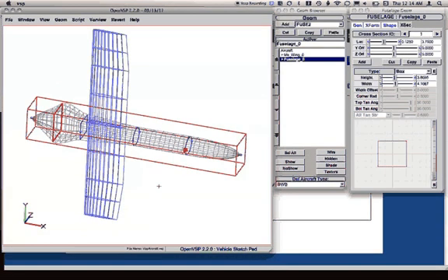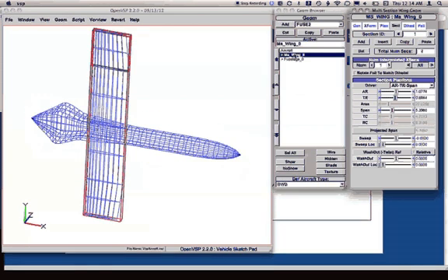Now, different components then, once you get the basic geometry here, again, all it does is it takes time to go through and do the actual refinement. So in this case, let's go back to the wing section here, and we'll come in and you can add different sections on the wing. So now we have 3 sections, so I can change this outboard section here,